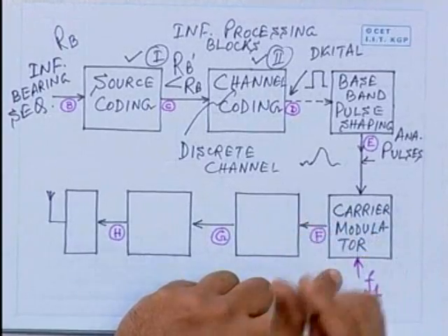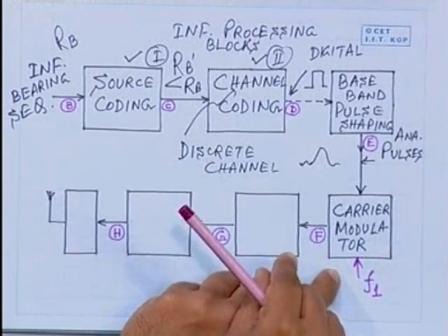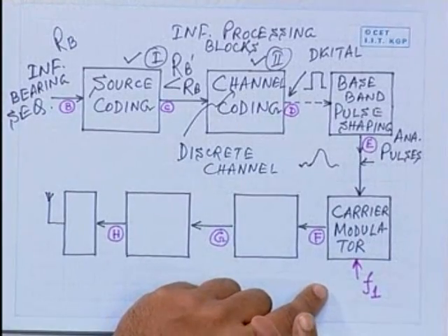The same chip which does the analog modulation may not do the digital modulation equally well. Is it vice versa? If we use it for digital modulation, we use it for analog ones. In some cases, yes, it may be, not in all cases. Those are the finer details about the specifications. In fact, the manufacturers design the ICs with some applications in mind. There are ICs available which are good for some low bandwidth frequency modulation, narrowband FM, which are also good for one digital modulation scheme known as FSK, frequency shift keying. Because things are very similar, it has been possible to design an IC at a low cost. So there are ICs available really.